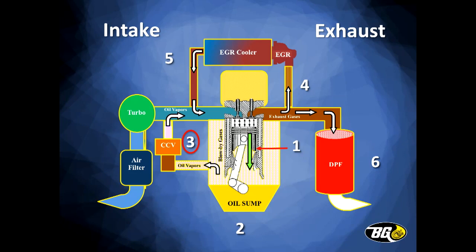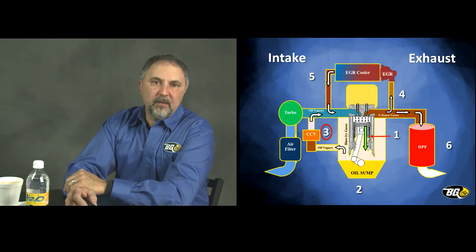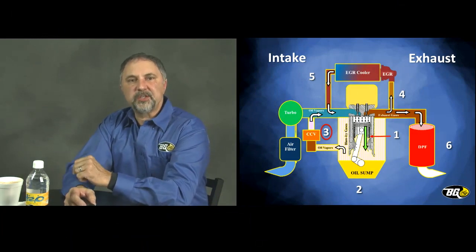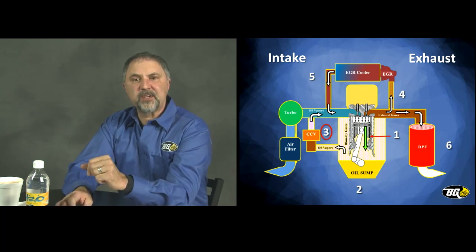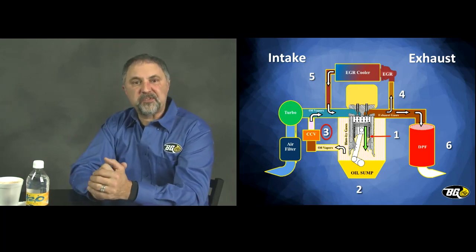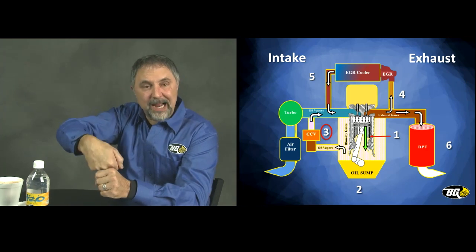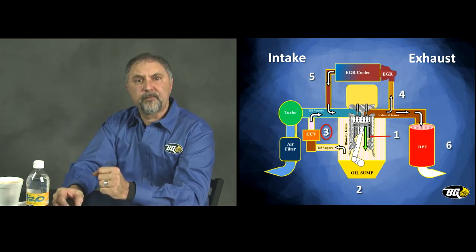If the system's plugged and the vapors can't breathe or escape, it'll blow gaskets out. That's when you see these diesel engines with valve cover gaskets leaking. And I've seen at times so much pressure inside these sumps that it has blown the dipstick out of the dipstick tube, which is why some of those dipsticks are locked into place. A lot of sump pressure there.